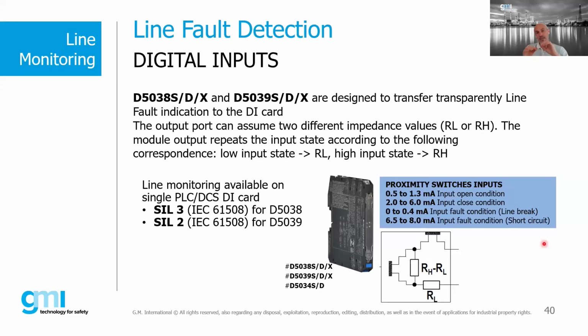We have also some devices that are specific for DCS or for PLC. Basically, that is a request for PLC, because DCS don't have such kind of monitoring functionality. But we have a solution for Triconex systems, for Honeywell systems, for Emerson, for Yokogawa. All those PLCs require different threshold values for detecting the fault, and this is also a function that is well required.